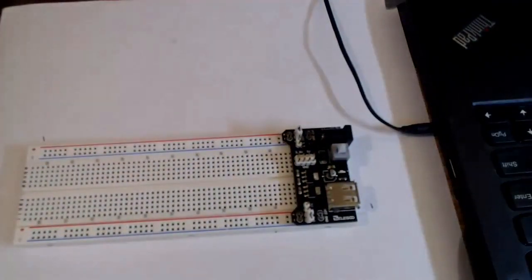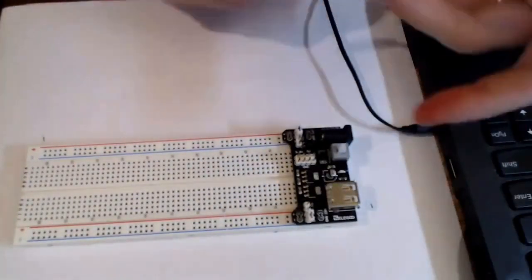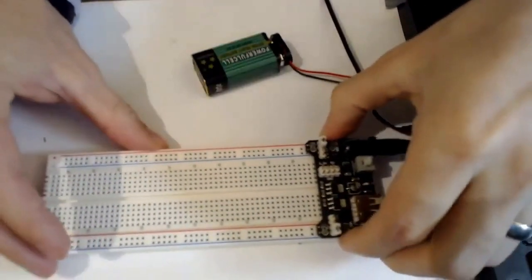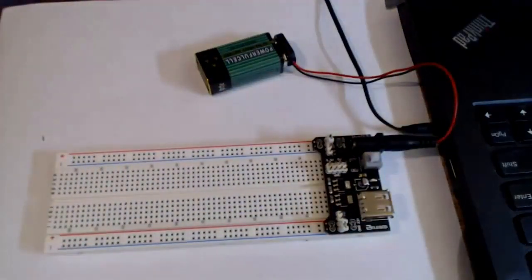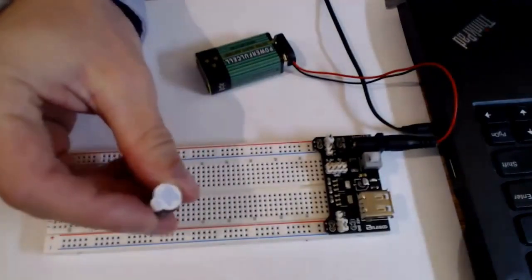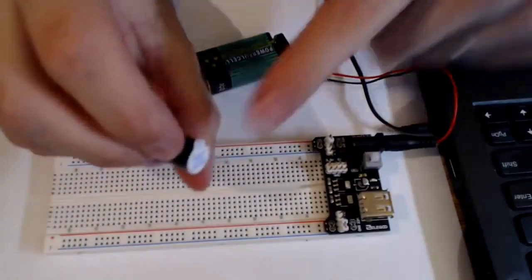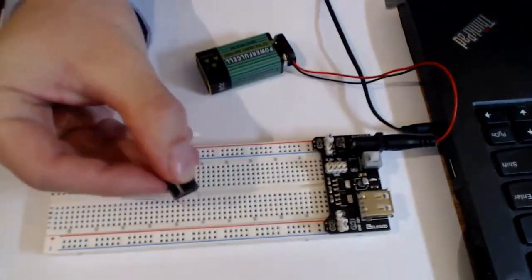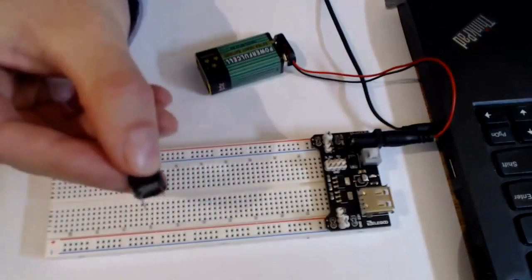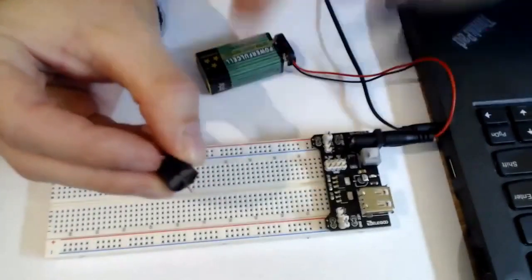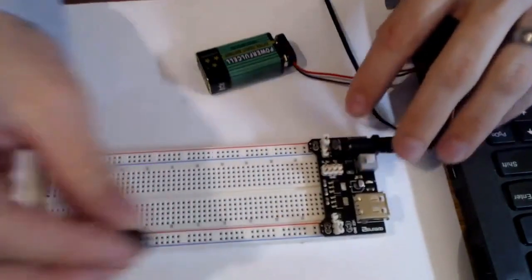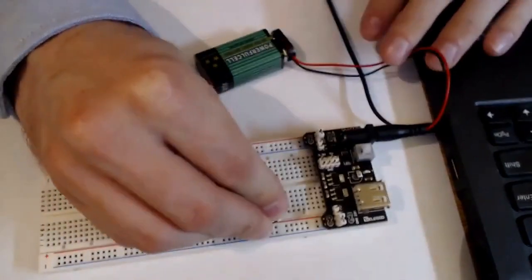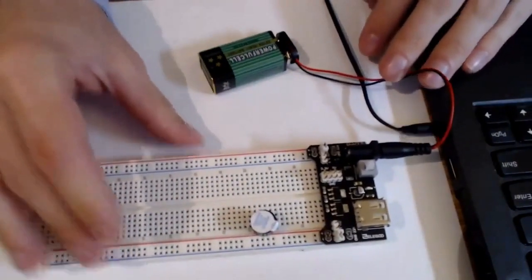And then you've got the 9-volt battery. And that's going to just plug into the adapter, like that. Next thing is going to be the little buzzer. The sticker has a plus sign on it on one side. That's going to correspond with the longer of the 2 legs. It's a little hard to see. The camera's not focusing that well, but one of the metal legs is longer than the other. That metal leg is going to go into J20, and then the short leg is going to fall into J23, like that.